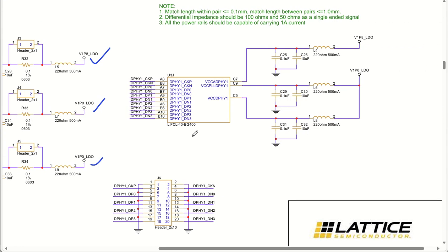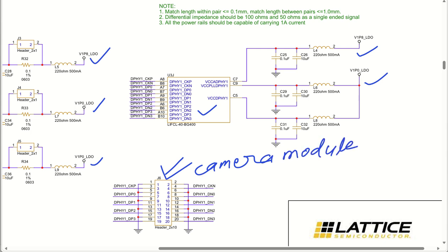Now coming back to another module of your camera module, so D5 0 is fine, then D5 1 is here. In the same way it is also powered with 1.8 volt and 1 volt with proper filtering and decoupling capacitors, and this is going to get connected to your external header that can be used directly to connect a camera module separately. So this is the camera module connector. All right, so this was all about the camera module that we have discussed.